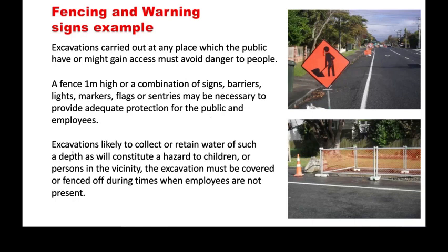Excavations likely to collect or retain water that might form a hazard to children or people must be covered or fenced off when you're not there. So usually they just use big sheet bits of steel and put those over the hole, and or even drive their digger up, put the digger on the steel, the boom, the bucket on the steel to stop it moving anywhere, and then put a fence around that.